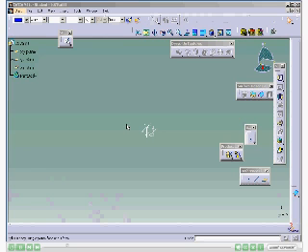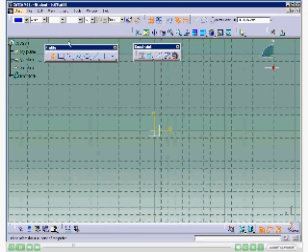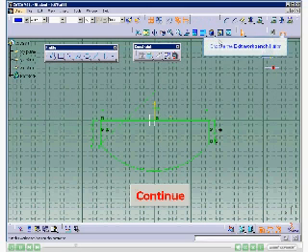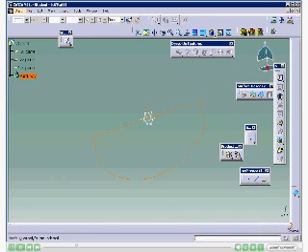Choose OK button. The base feature of the model will be created by extruding a sketch drawn on the ZX plane, with the Mirrored Extent checkbox selected. Now choose Sketch button, and select ZX plane. Now draw the sketch in the Sketcher workbench, by using Profile and Arc tool. Exit from the Sketcher workbench. To dock the unwanted toolbar from the geometry area, double-click on the toolbars.